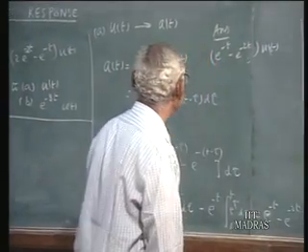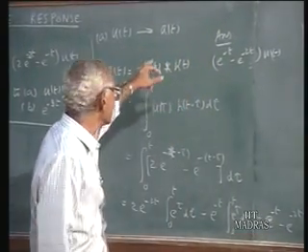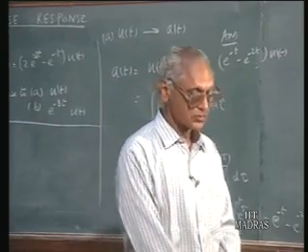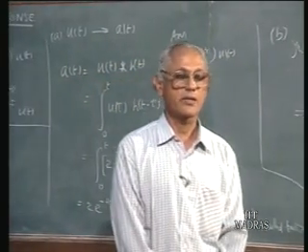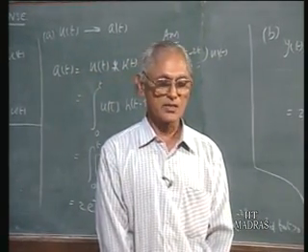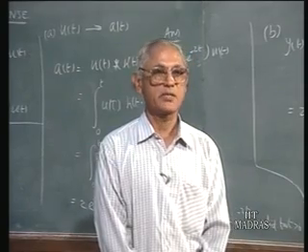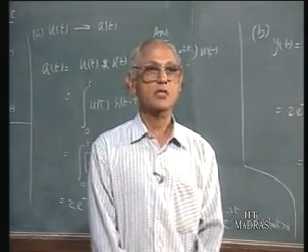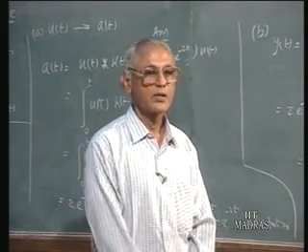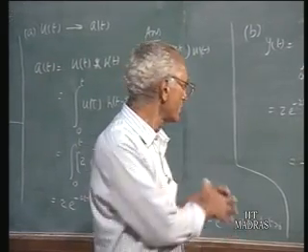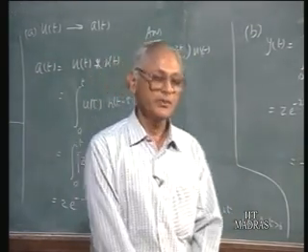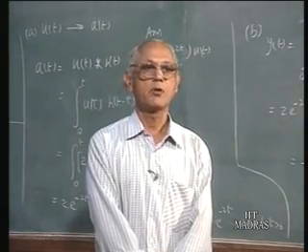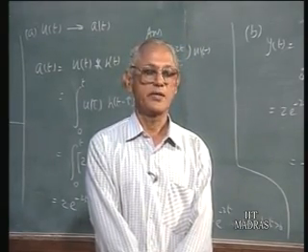Step response is called a of t, as we have mentioned here. Almost identically we can carry out the analysis. We have also some kind of convolution integral involved there, but we will do this later after we study Laplace transformation methods. So impulse response and step response also can be used to characterize the linear system, and here again we are calculating all this in time domain only. So these are all different ways of describing the input output relations of a linear system.